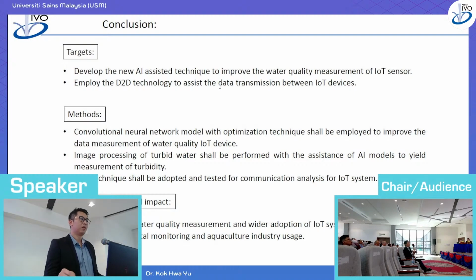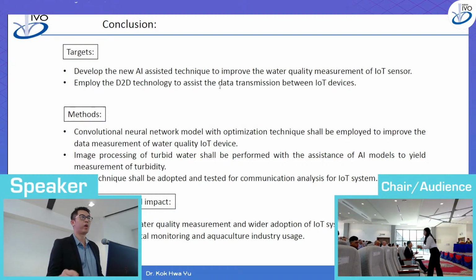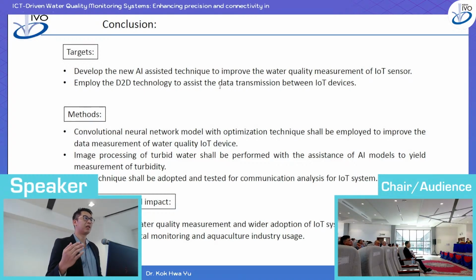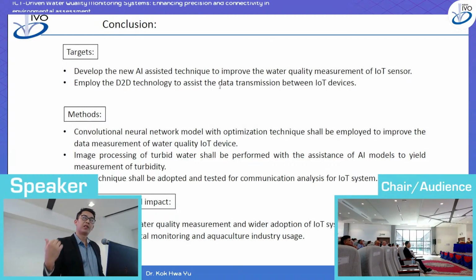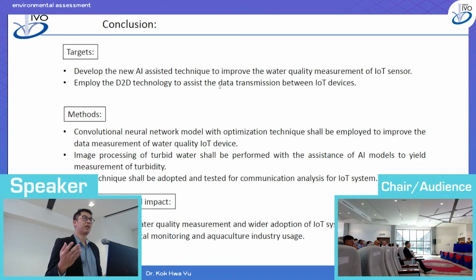Thanks for the question. We have tested several sensors, normally IoT sensors. Normally, IoT sensors are not that reliable, and the predictions made by IoT sensors are offset by a lot, but not all types of sensor. For example, the turbidity sensor will have deviation of more than 100%. And it's quite sensitive in the sense that it's affected by the outdoor light. So if it's daytime, you're affected. Normally we have to have an enclosure, put it inside, then we can have a better estimation.